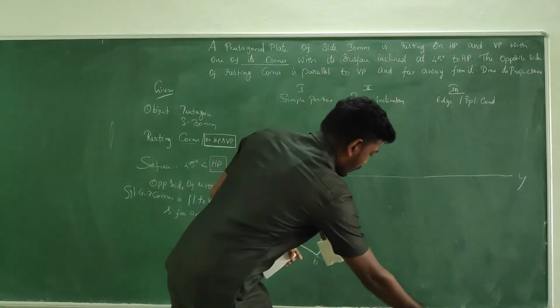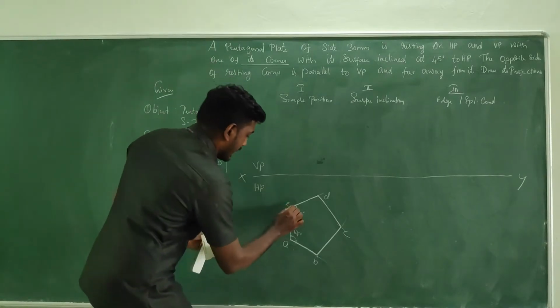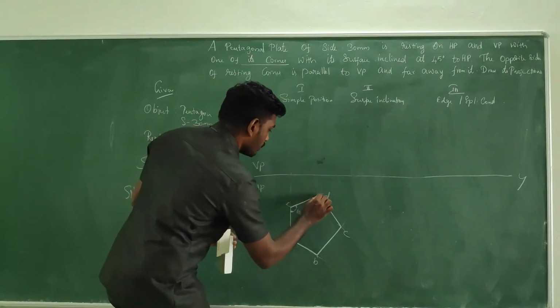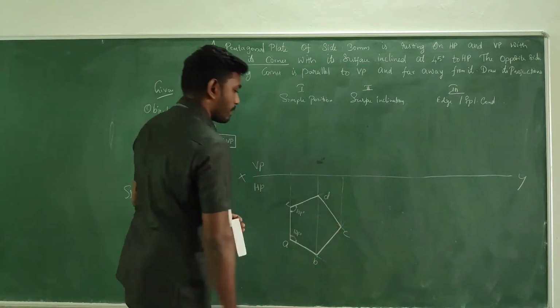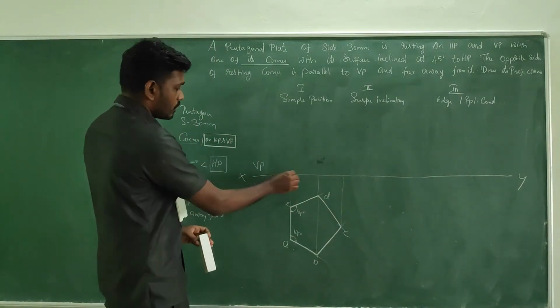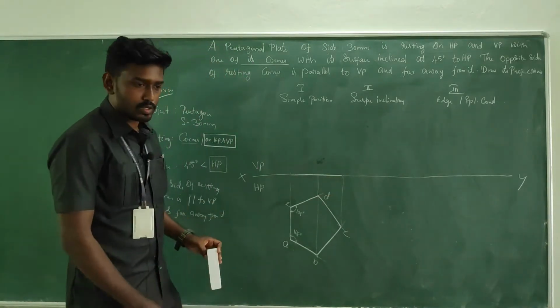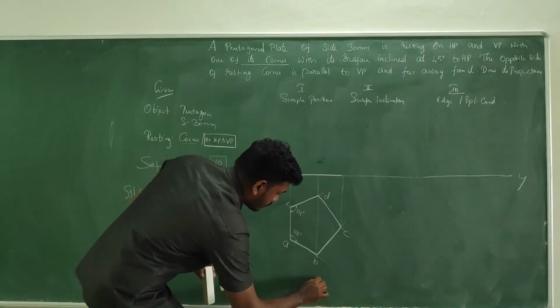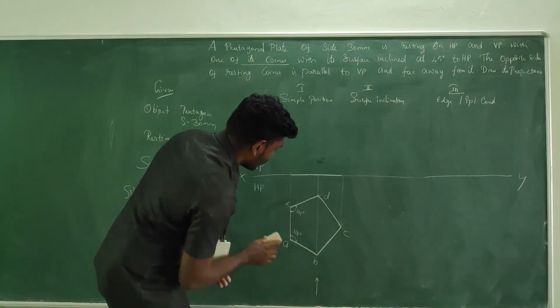Okay, so now the top view is over. Go to the front view. Take the projectors from each corner. D and B will be the same projector. It's a straight line. Go for a straight line between the projectors. So this is the observer position for this front view.